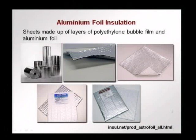So, there are many products available in the market. These are combinations of bubble film. Bubble film is where you have a polyethylene layer with air gaps. This provides for insulation by cutting off conduction, and then we have the external layers of aluminum foil which cut off any radiant energy that could go through, and these are available in the market and can be used readily.